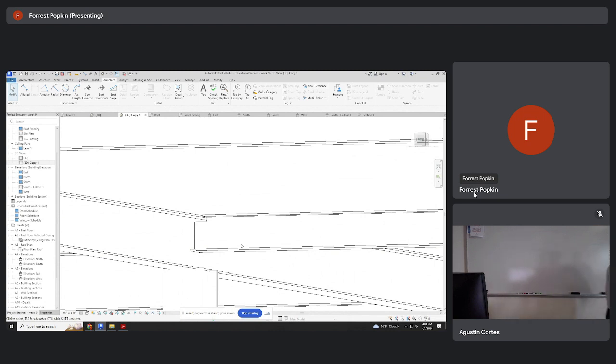So if I'm building an apartment and I just have sheets of plywood as my substrate, and I'm just going to put carpet directly on that, that's not nearly as soundproof as if I put at least a few inches of thickness. And the reason why gypcrete's used is because you don't need it to be that thick, but at least it provides something. The main reason is for this term.